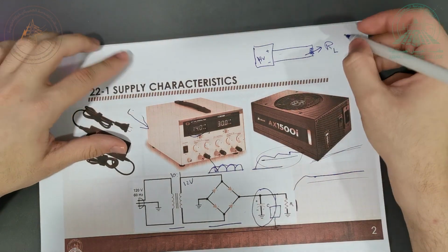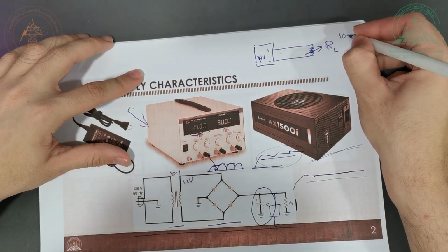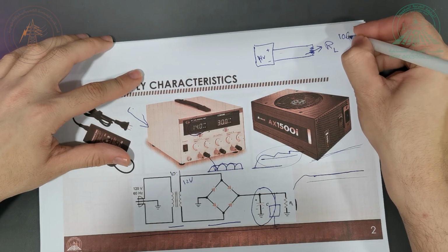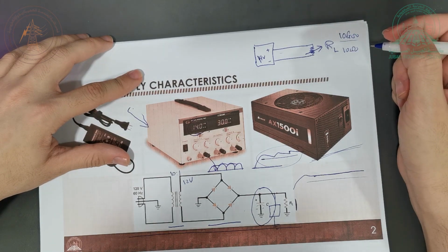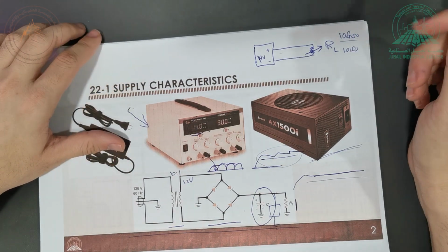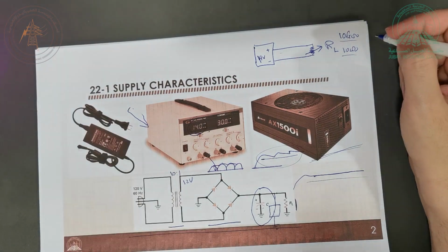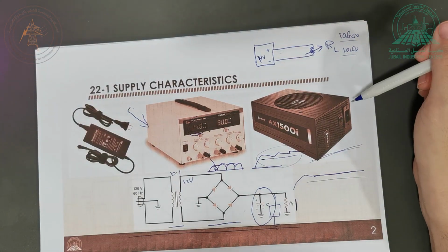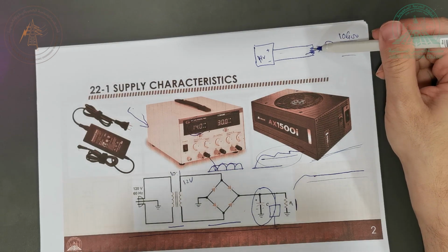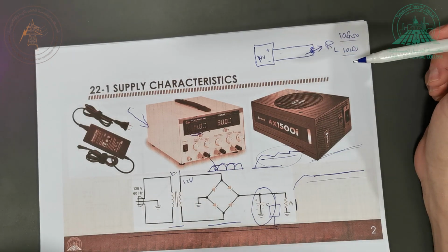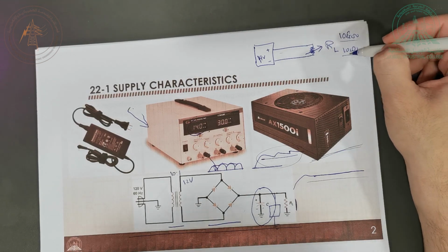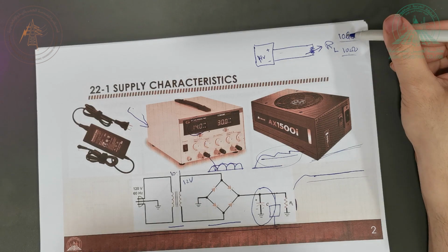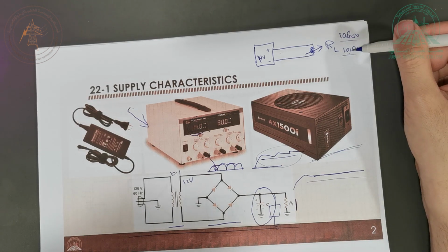So imagine that you put a very, very large output resistance, similar to an open circuit, like 10 giga ohm, and compare it to 10 ohm. This is a very high resistance. This is a very small resistance. Now, in an ideal case, we should get 14 volt in both cases, whether you put here 10 giga ohm or 10 ohm. But in reality, you're going to see, no, actually the voltage is going to be different. The voltage here is going to be different than the voltage here. Actually, the voltage here is going to be high, the voltage here is going to be a little bit less. So this is going to be almost 14, this is going to be less than 14.